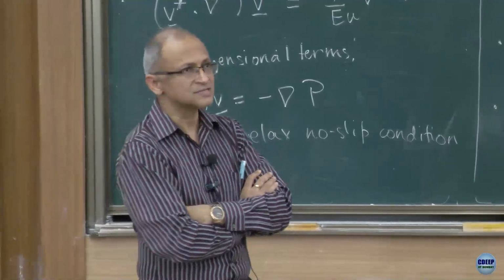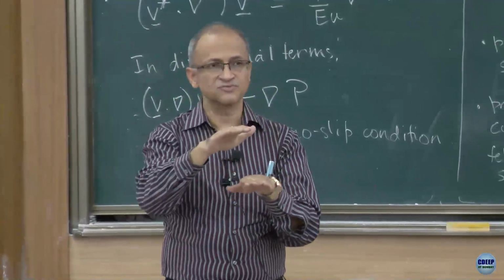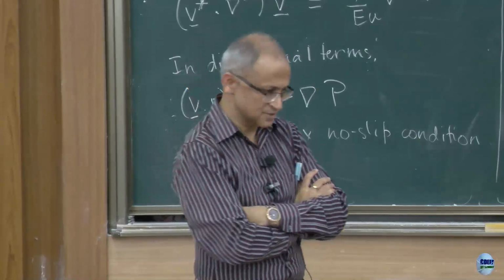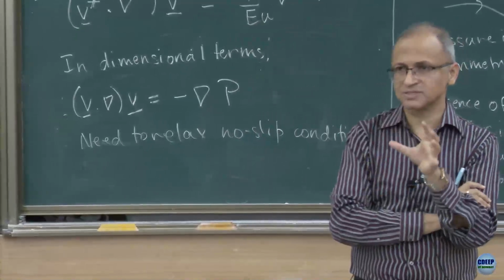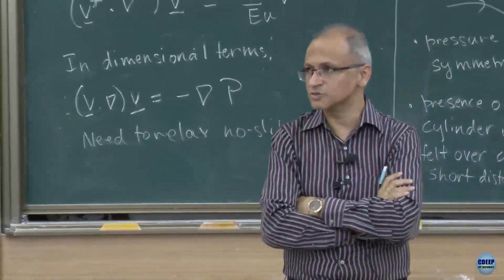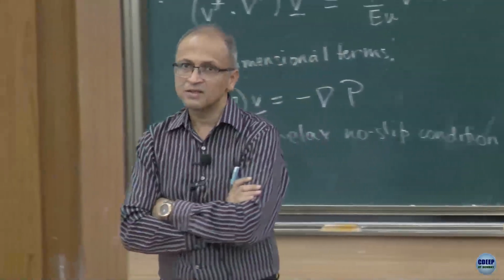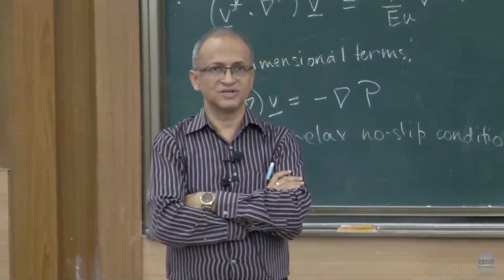An example of that you saw in the midsem, where we had a plate driving the flow and also a pressure gradient driving the flow. So there is a Couette flow and there is a Poiseuille flow, and the solution is essentially a sum of these two solutions because the inertial term was not there in a fully developed channel flow. So that's basically what you get in the case of a linear equation.